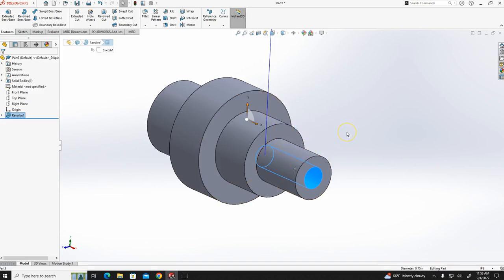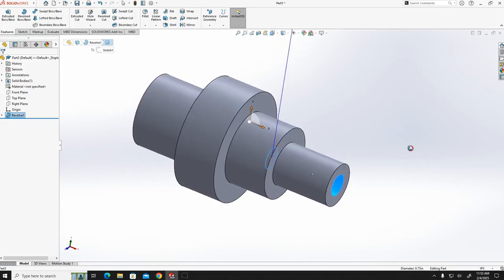Based on the units used, the tap will be of inches or of the metric system, millimeters, and similarly for external threads the die will be of inches or metric, which is meters or millimeters. As we have used the inches IPS unit system, we will have to use the inches die. So let's create the thread.